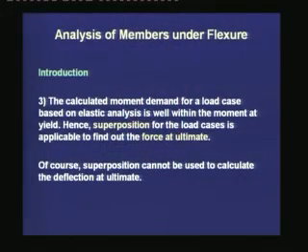The third argument is that the calculated moment demand for a load case is based on elastic analysis, that is well within the moment at yield. Say if I pick up the load case for the dead load, or if I pick up a load case for the live load, then the moment demand for any of these particular load cases is well within the yield moment, and hence superposition for the different load cases is applicable to find out the force at ultimate.